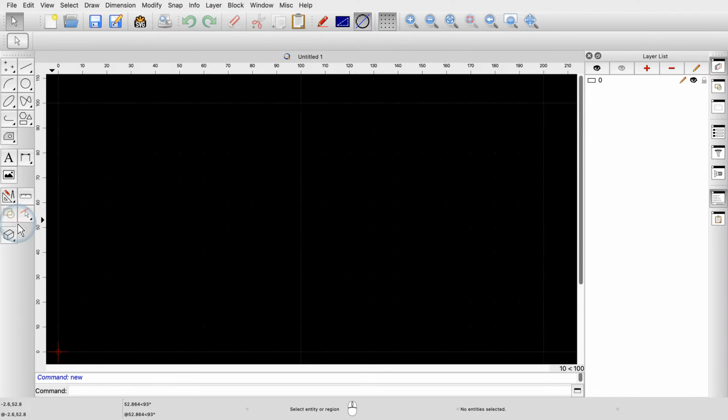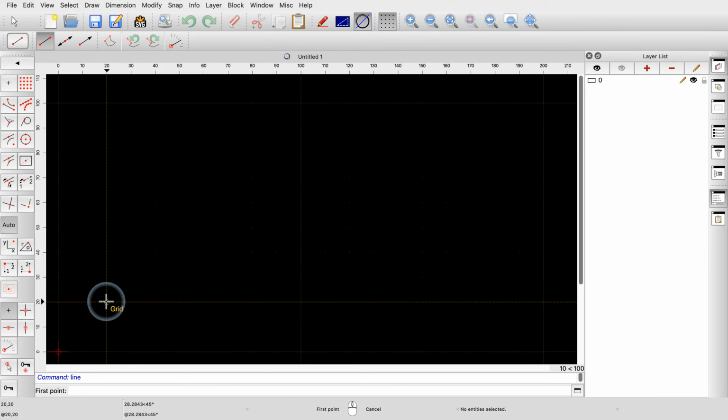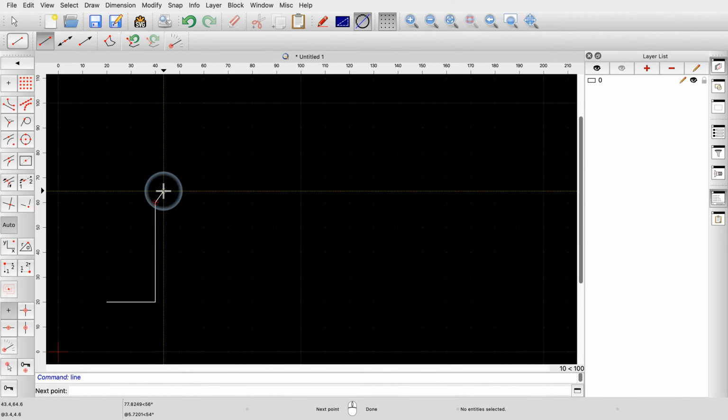Now let's draw some lines. First, we click the Line menu button in the CAD toolbar to show the line construction tools. Next, we click the button for the tool to draw lines from two given points. QCAD is now ready to start drawing lines. The first click into the drawing area sets the start point of the first line. Every click now adds a new line to the drawing. When we're done, we click the right mouse button to stop drawing connected lines.